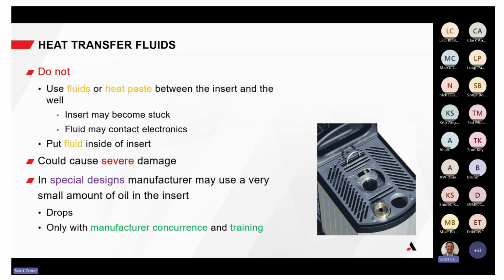Because of the tip design that we talked about on those sanitary seals, there are occasions, because of the inconsistent machining, that we do have to use a drop of heat transfer fluid in those inserts. That's the only practical example I can think of. Any other time, you don't want to put fluid in a dry block. The wells outside of the convertible units are not set up for that. And you could have fluid contact electronics, and that can cause a fire.